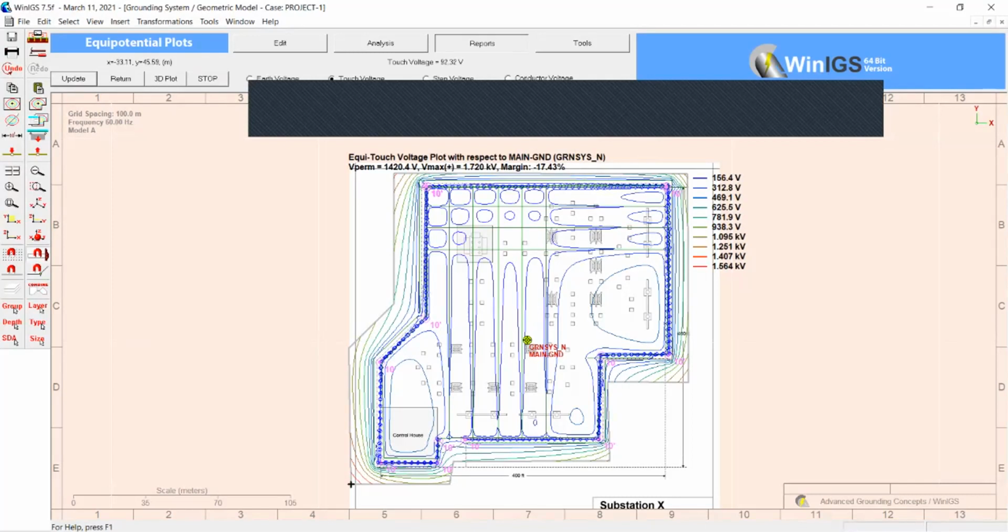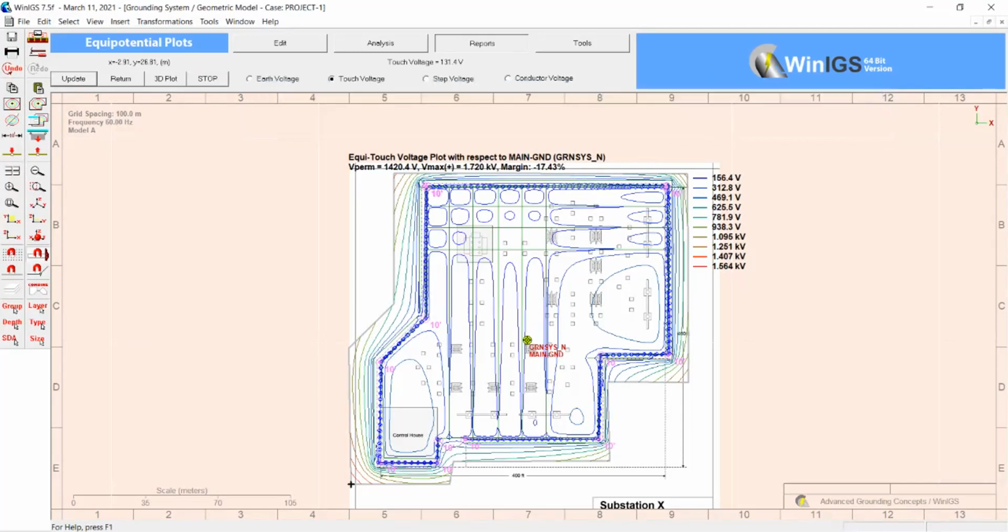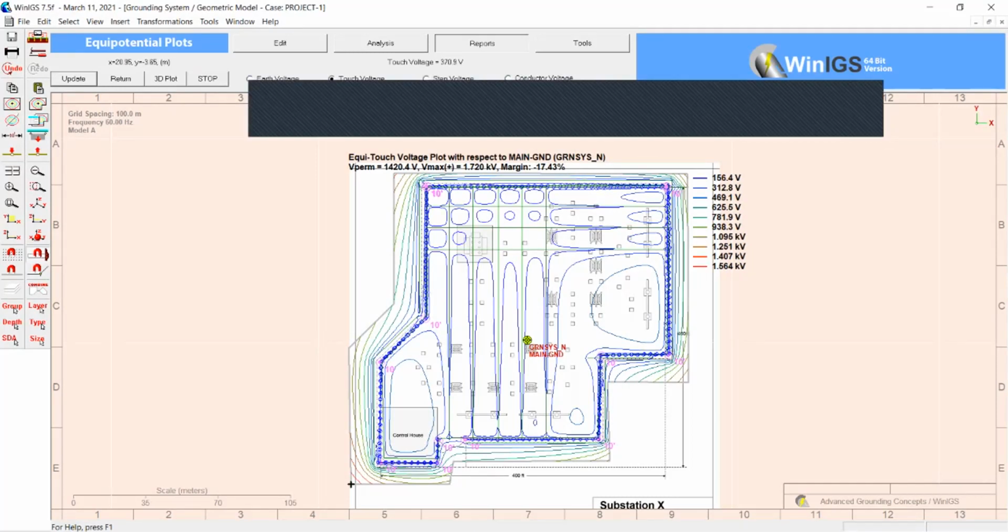You have to put the conductor closer. Okay, and on the other hand, you can change the soil resistivity within the tolerance. So different ways you have to act in order to achieve the touch and step voltage, which must be less than the permissible, or at least could be equal to the permissible, also is acceptable. Okay, so that's how we'll do.